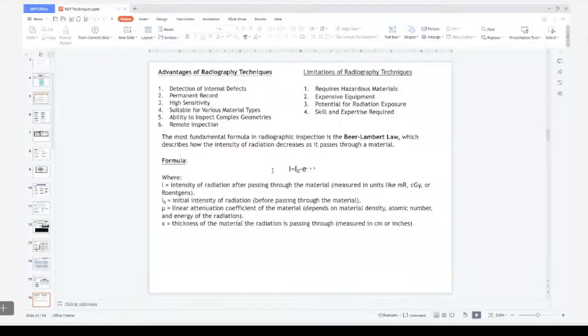Ultrasounds are typically used to detect internal defects or thickness of the material, and any bonding issues in CFRP. Typically, UT is used. So for any casting components you go for radiography, for any forging components you go for ultrasounds. Similarly, for composites also people go for ultrasounds. The reason is, in castings you get porosities and voids, which are three-dimensional defects, whereas in ultrasounds you get two-dimensional defects like cracks, delaminations, and so on.